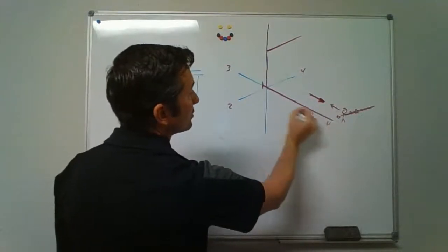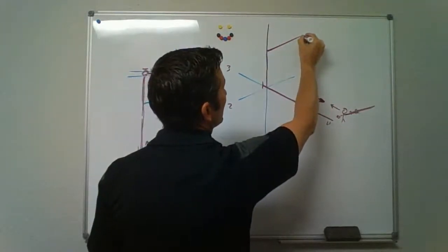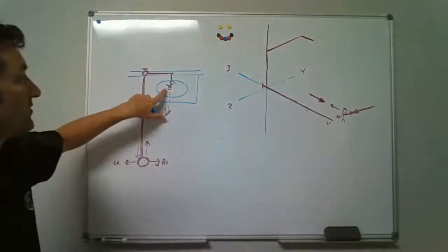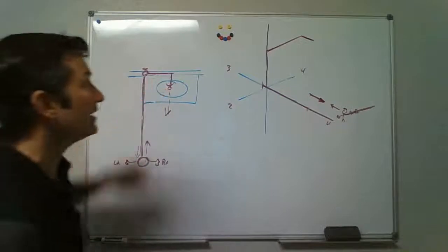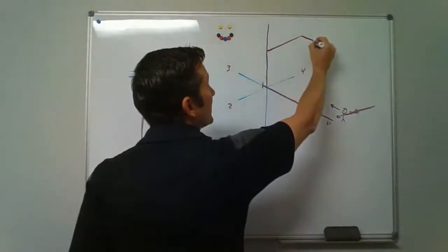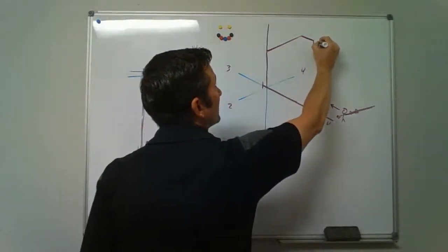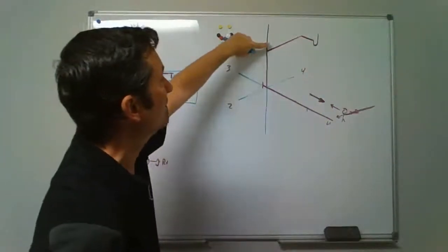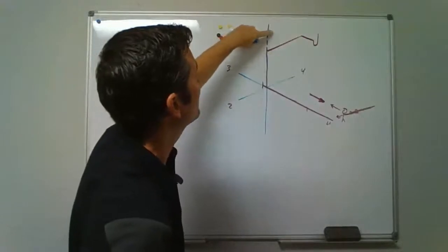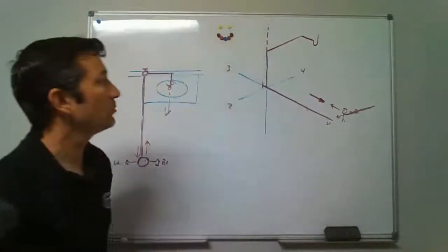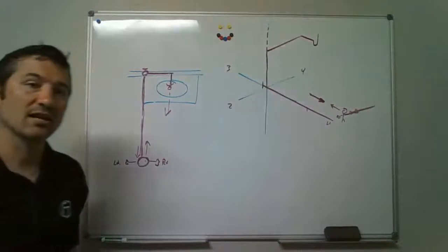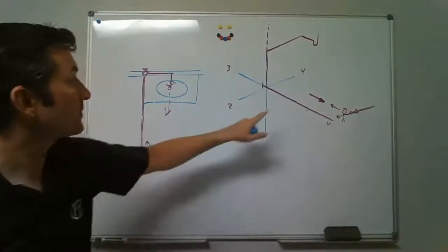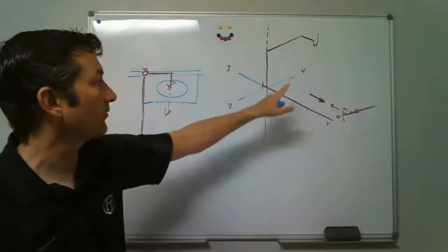Look at the line direction you're following. So it's going to come and follow this line coming out. What is that the symbol for? A P-trap on the end? P-traps are straight down, a dip, and straight back up. Now, above the drain connection coming in is just plain vent, and that is represented by a dashed line. Okay? That was one angle of 4 possibilities.